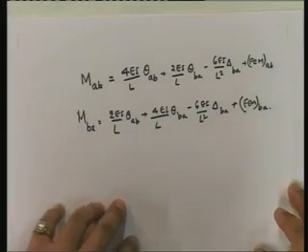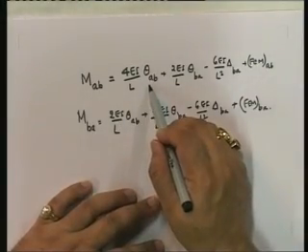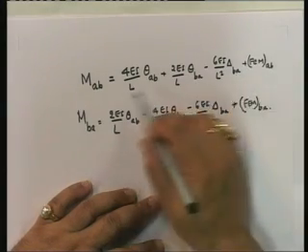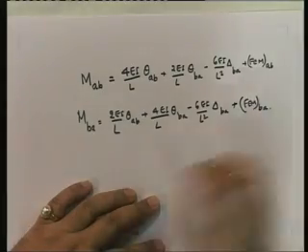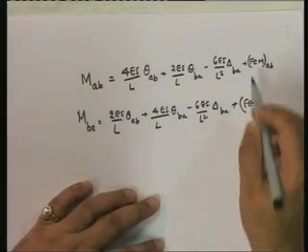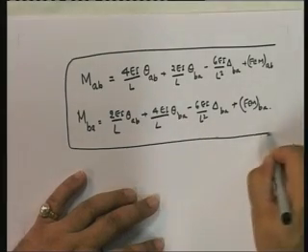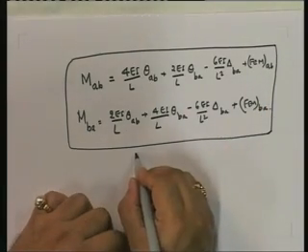These are the complete equations. Look at this. If theta A B equal to 0, theta B is equal to 0, and delta equal to 0, that's the fixed case. What is M A B equal to? The fixed end moment. That's what it should be. Similarly this. So this is the final equation,